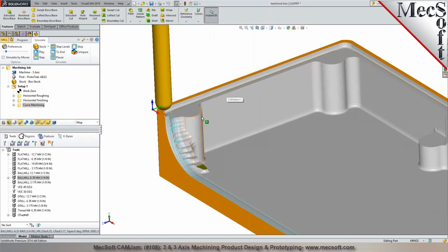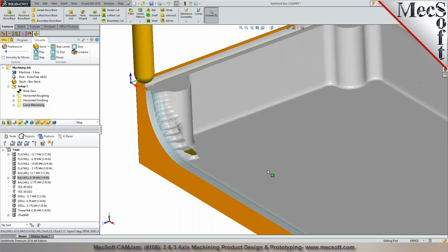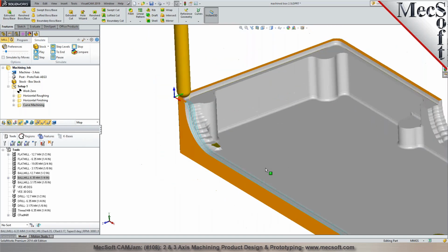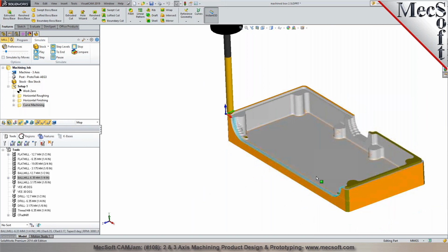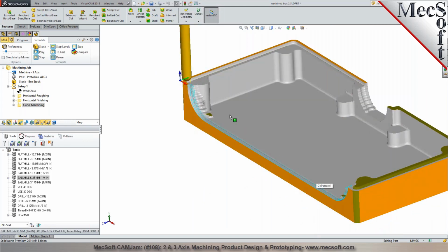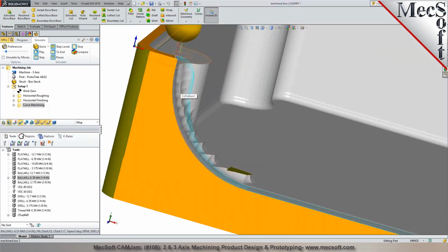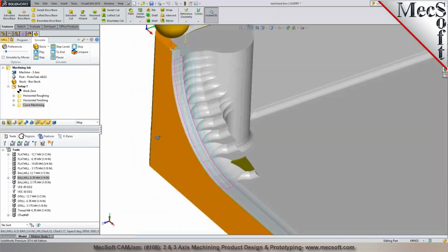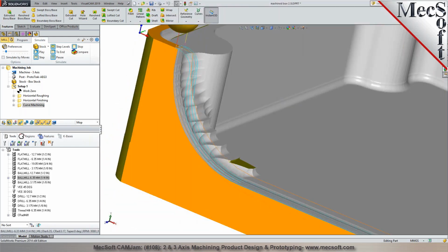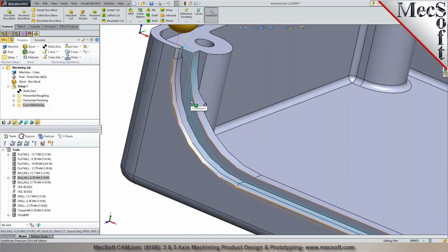So these are some of the advanced 3-axis capabilities that you have in the Pro, where you can determine what type of toolpaths you would like to accomplish or generate. Now, to try to do this in the 2D programming paths, it would be fairly difficult, correct? Well, you can't really do a 2D operation unless you flip the part and machine it with the side of the cutter like a profile. Right? You put it on the side. Because over here, you see, if you're doing a 3D cut, the tool tip is what I display in the toolpath here. So it automatically compensates for the tool based on the geometry that you're following.